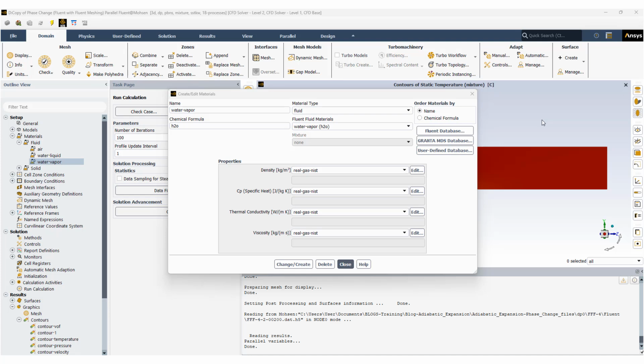And also, if we have a wider opening, like a ratio of much more than 4 to 1, for example 10 to 1, you may see a different behavior for the condensation and phase change. And back here to real gas, if I want to use this real gas NIST model for refrigerant, we also need to have material properties for the vapor condition if we want to consider refrigeration with phase change, for the evaporation or for the condensation. This is something you have to note here.